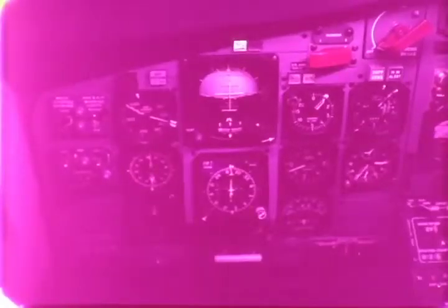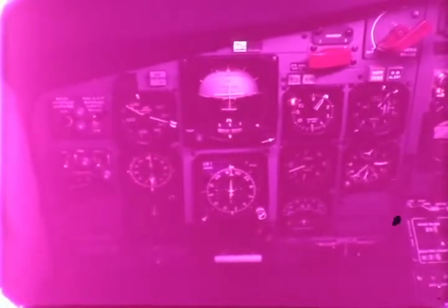Approaching decision height. Visual check, nothing. Decision height, another visual check. There are the approach lights. The pilot goes visual but has no horizon or aim point. He is unable to judge the necessary flat glide path and lands short of the threshold.